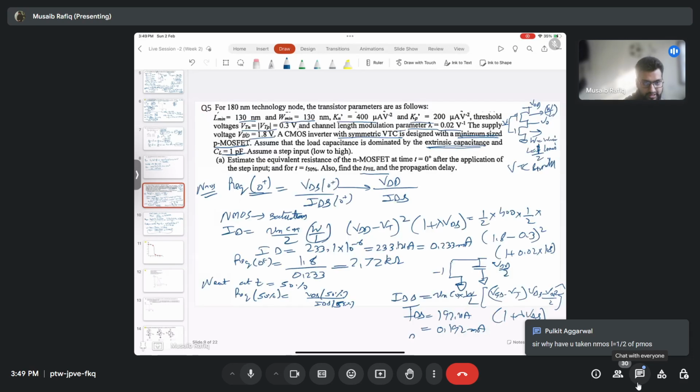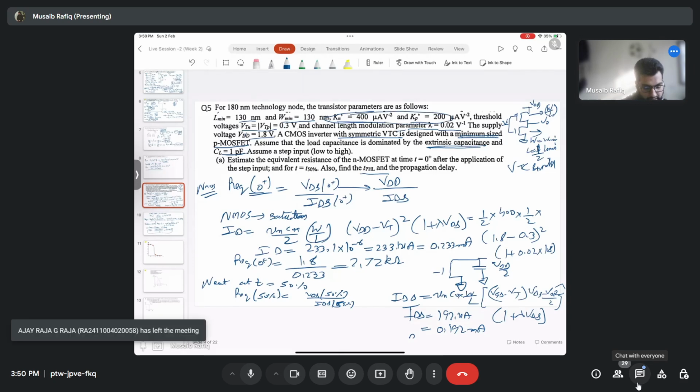Yeah, I thought this question would come up. Just check the question. The CMOS inverter characteristics are symmetric, and given is that my PMOS is minimum size. So my W and L for the PMOS is fixed. Now to make it symmetric, L of the NMOS needs to be changed, and you can figure it out from this W by L factor, because kn prime by kp prime is equal to 400 by 200, it comes out to be 2.